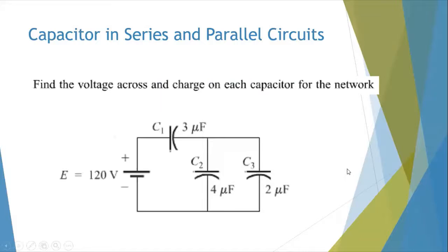Okay. In this circuit, you find a combination of capacitors in parallel and series. So again, if you assume a current going out, it goes through this capacitor C1 that's split into two paths. So you could easily combine these two capacitors C2 and C3. Since they are in parallel, you just sum them together and get 6 microfarad, and then you can do the reciprocal to get the total. C1 and the 6 microfarad, and from there you get a similar circuit as before.